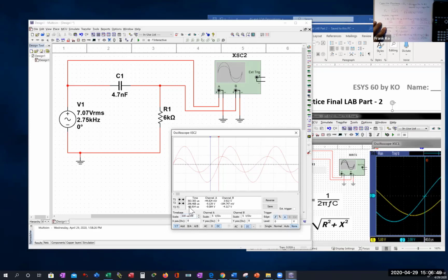It doesn't matter that it says negative or positive. If I move this over to this side, say there, and I move this guy over to this side, say right there, as best as I can nudge it, I'm still getting something very close to 68 microseconds, yes? Okay, and then now there's no negative, only because the red cursor is before the blue cursor. So negative or positive here doesn't make a difference. What is important is this number.